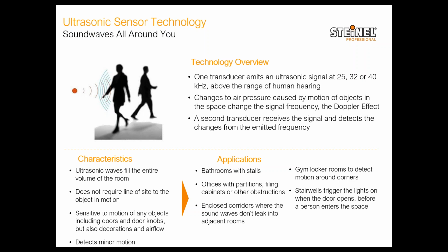Offices with partitions, filing cabinets, other obstructions, ultrasonic would be a great fit. Gym locker rooms, and then stairwells. Stairwells, the nice thing about using ultrasonic technology in stairwells is that the lights would turn on before you even set foot in the staircase.